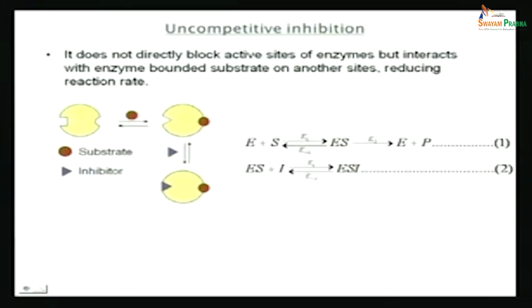Any combination I give you, these are some examples we are doing which are prototypes, but if we go beyond these prototypes and come up with more complicated things, what you have to figure out is: A, what are the reactions that attain equilibrium; B, what are the species that attain quasi steady state; and C, which is the reaction that is the rate limiting step which will govern the rate of product formation.